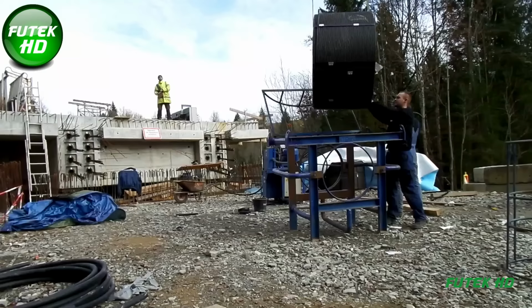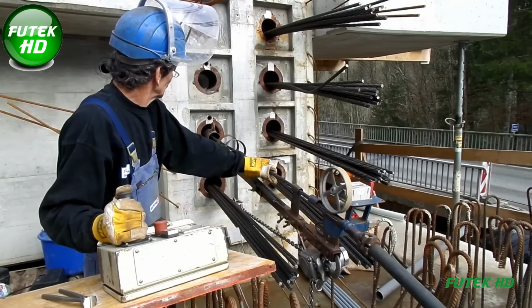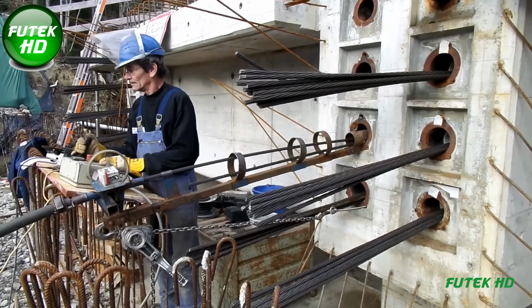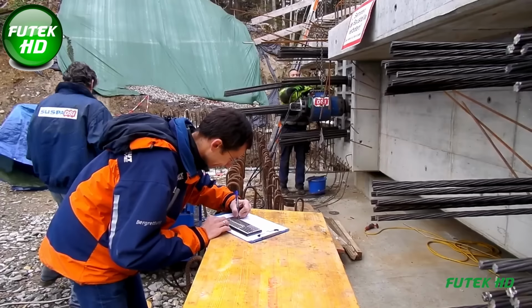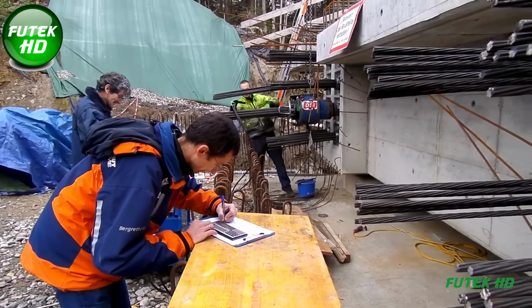Piers, false work, and supporting structure. March to December 2014, with foundation work completed, attention shifted to the piers and abutments, which were finalized by May 2014. The next major milestone was the erection of false work. Due to topographical constraints, conventional lifting of the massive lattice girders was not feasible. Instead, a sliding method was employed to assemble the false work, a technique that required meticulous planning and precision.